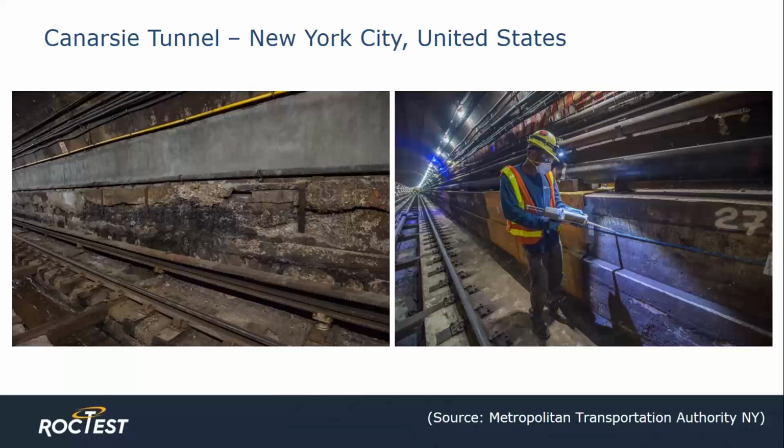The photo on the left shows the condition of the tunnel before repairs. The photo on the right shows the application of epoxy to affix the Hydro&Geo cable on the tunnel walls and RFPs. In a typical installation, the epoxy is more than sufficient to permanently affix the cable to the structure.